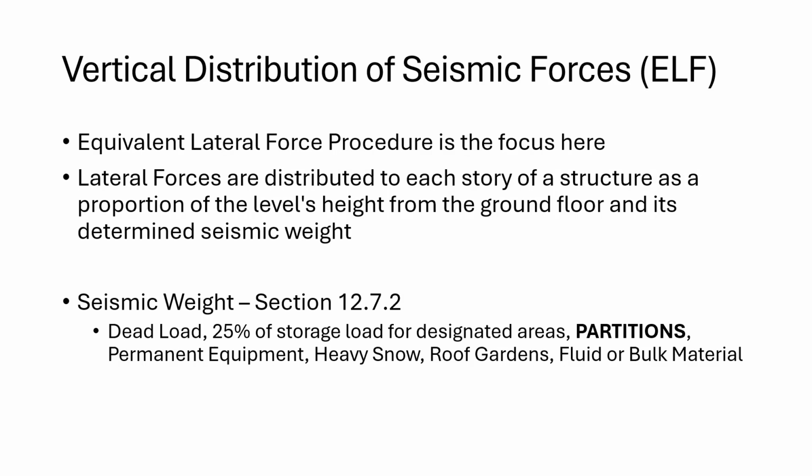So we need to quantify that and distribute that lateral force vertically along the building height. So we do that by equivalent lateral force procedure. This is a fancy way of saying the lateral forces are distributed along the levels or heights of the structure proportional to each level's weight and height from the ground.